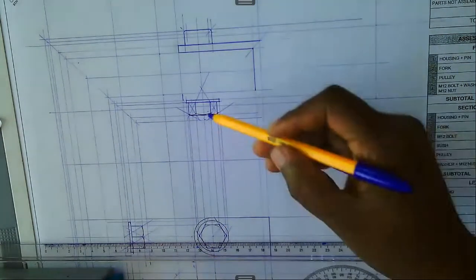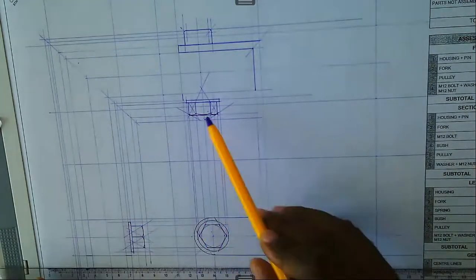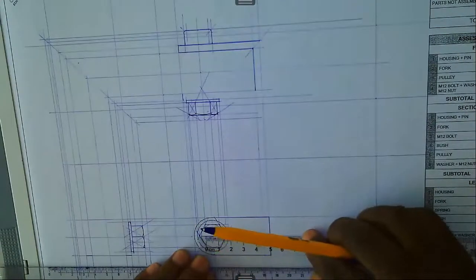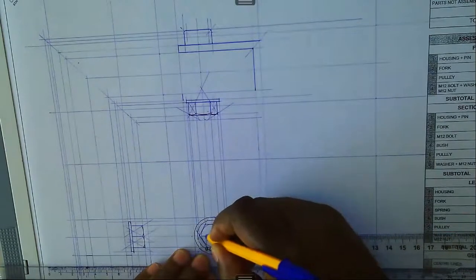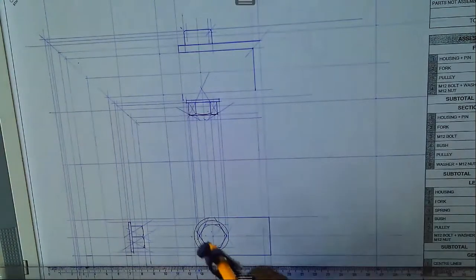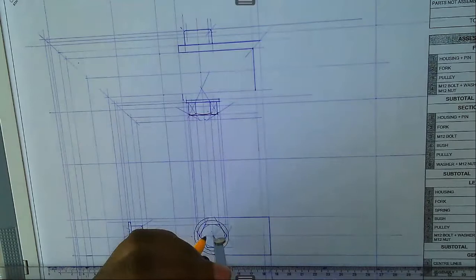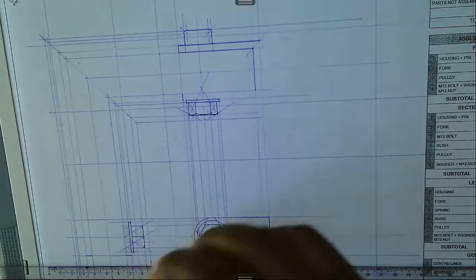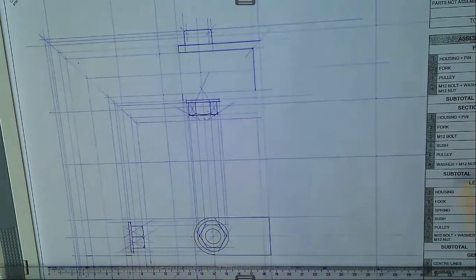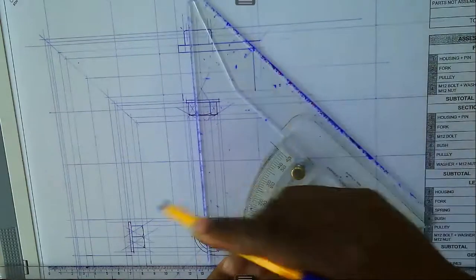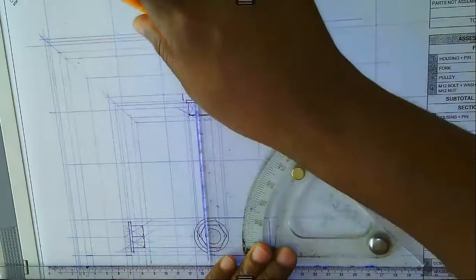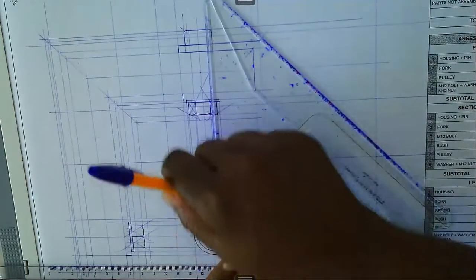Now that we know the full extent, what if we need the detail with regards to the bolt? It's M12, so radius 6. Radius 6, like that. It's an external thread. So we open to this. And we draw a circle like that. That is the nominal diameter. But once we have drawn this, you can now project it there. Project. Like this. We do the same. Also project like this.